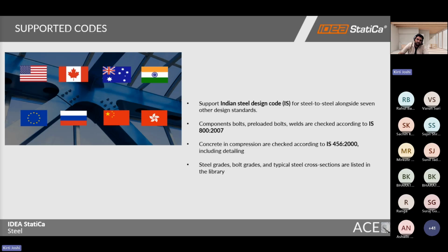Basically, in steel projects, for example PEB, industrial, and oil and gas projects, your joints often involve heavy shear or require large moments, and basically thick plates, and they may even require multi-row bolt arrangements. So if you are analyzing by just the traditional hand method, you may struggle to capture effects like local yielding, prying action, or plate buckling.